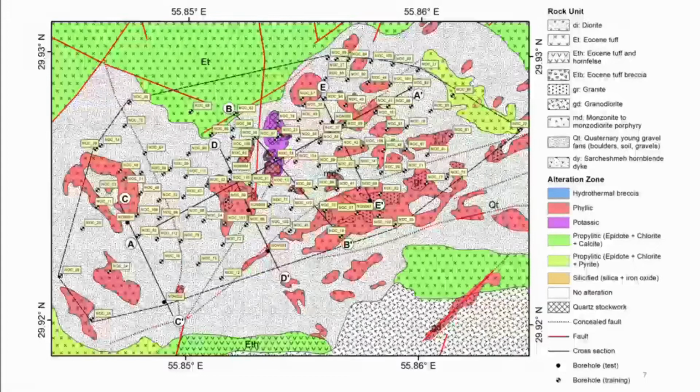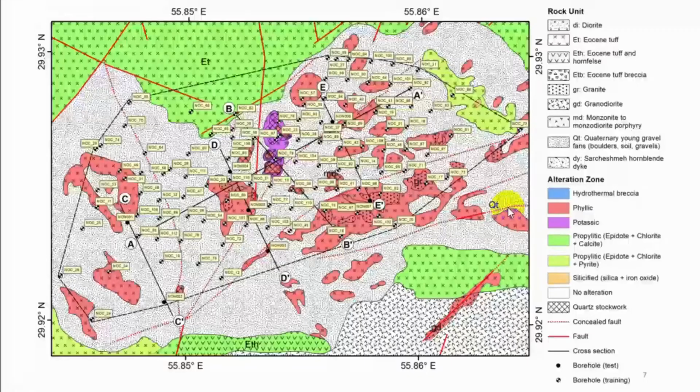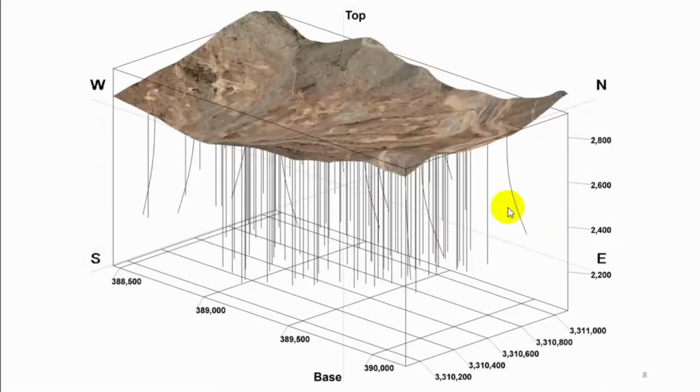And our modeling space is constrained on the upper surface to the topography, and also we restricted it using the convex hull and polar coordinates. And the depth of our model is also constrained to the depth of our boreholes. In total, we have 500,000 voxels in our modeling space. And here is the topography of our study area and also the boreholes we have.